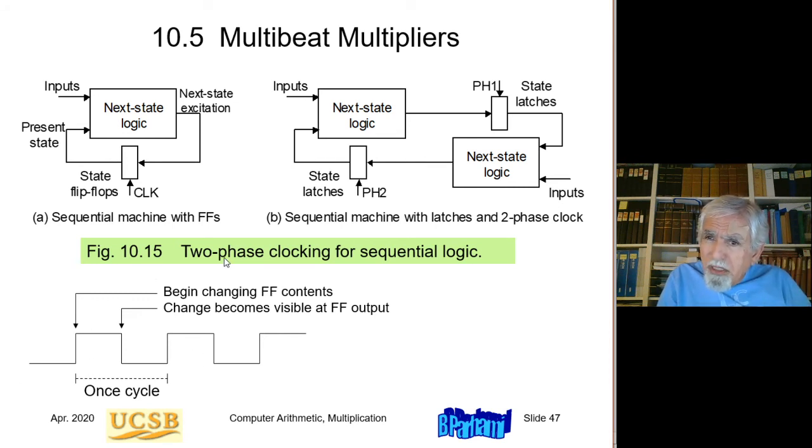From your course on logic design, you should know that any sequential circuit has one or more state flip-flops, and a next state logic that determines what should be stored in these flip-flops, what the next state should be, based on inputs to the circuit and the present state of the circuit. So the present state and inputs dictate what the next state should be, and this is synchronous. Every time the clock ticks, a new next state is computed and is stored in the flip-flop.